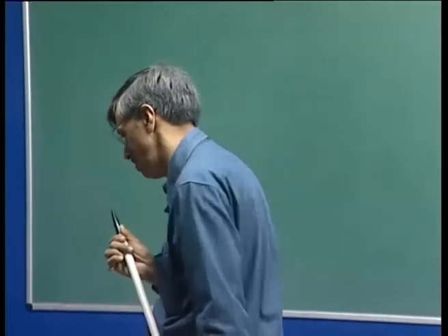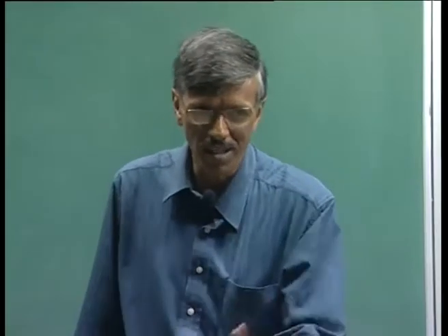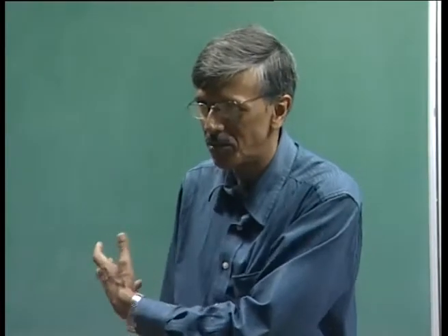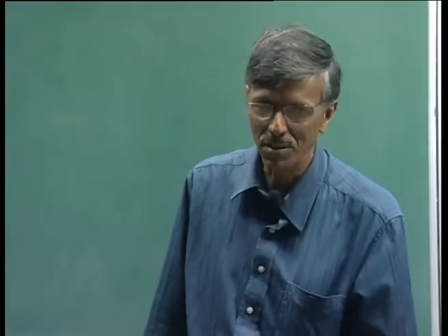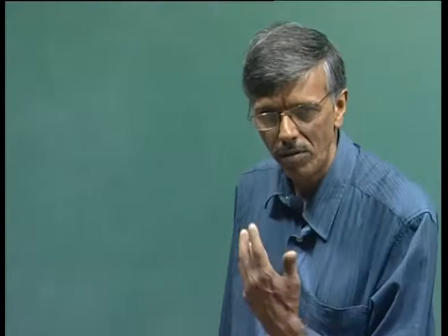In fact, one of my serious thinking about the whole topic of separation is that separation happens because of this phenomenon, that you have upstream propagating unstable modes. This has to be systematically done. We have not looked at it seriously, but if we focus our attention on flows with different pressure gradient, we may actually find out more interesting properties of upstream propagating modes.